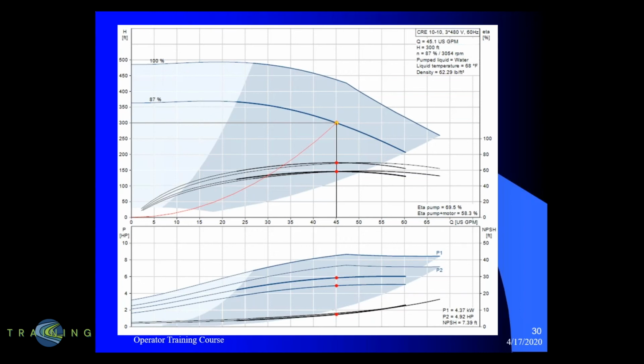And so when all of those get together, along with all the other stuff that's dumped into a wet well, including grease and all kinds of other things, you start getting what our guys in the field will call a mop head. All those things start going together and creating a solid that gets significantly larger than the 3 inches that we say will pass. Also it is true that sometimes you'll get real stringy materials in these tough items like the non-flushables that people flush, that'll get stuck between tolerances between the impeller and the bottom plate.